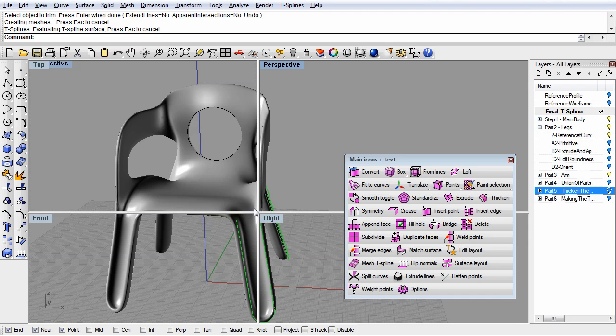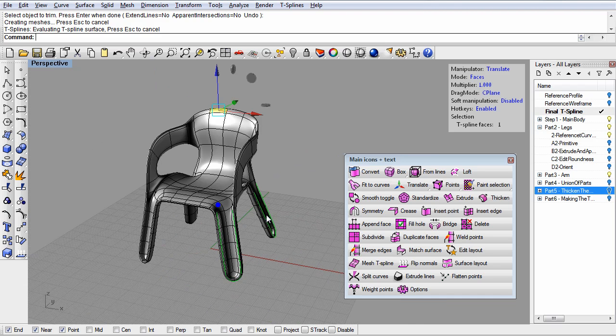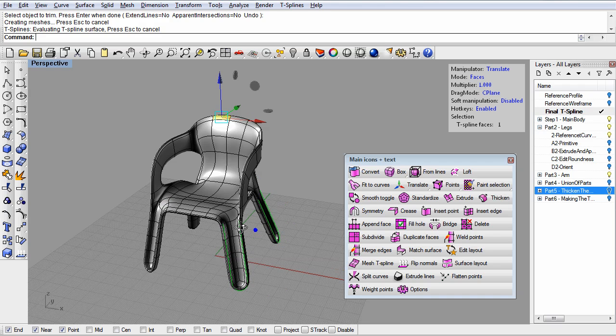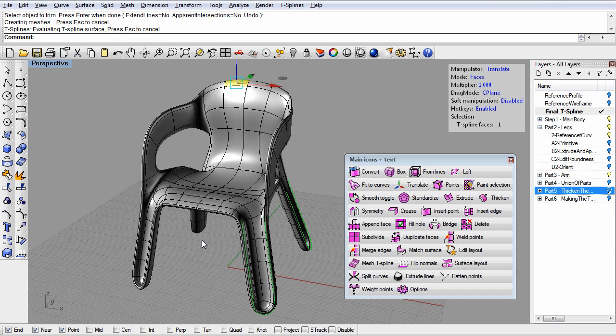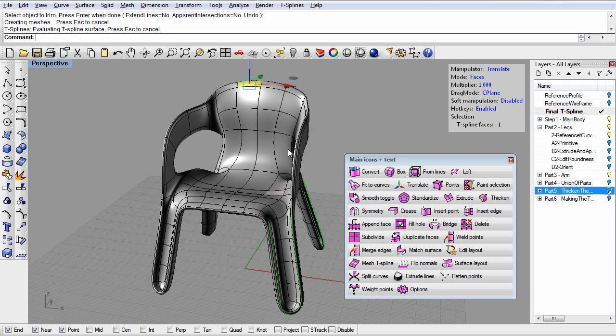One other thing is this T-spline will go downstream to any other modeling package beautifully. So if you wanted to go to SolidWorks or Pro-E, and you want to thicken it using their tools, you could just export this model as a surface or a solid, and I've never heard any reports of T-spline models that have not been completely watertight as they've gone to other programs downstream. So you could have exported this as an IGES or a STEP and read it into other CAD programs, and pushing T-splines data downstream like that works really well.